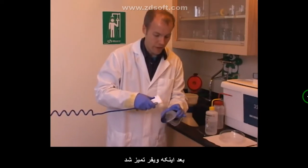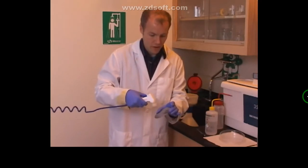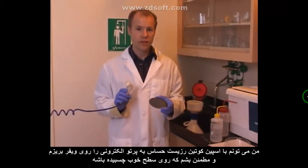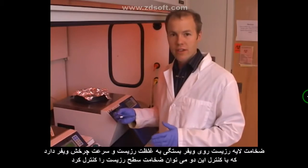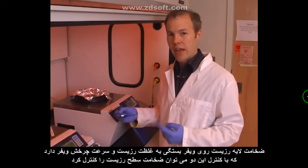Once this wafer is clean, I can spin coat it with the E-beam sensitive resist and make sure that the bonding to the surface is good. The thickness of the resist layer on the wafer can be controlled by playing with the viscosity of the resist that we're applying and also the speed that it's spinning at.